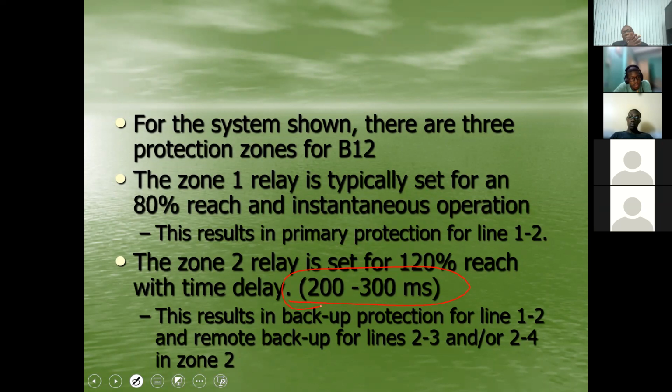And what is happening here, students, and again, we're going to get into the details, is that the relay is giving the opportunity to the other impedance relay in Cane River to operate instantaneously, because it senses that it's a zone 2 fault. So in other words, it's on the other line, right?